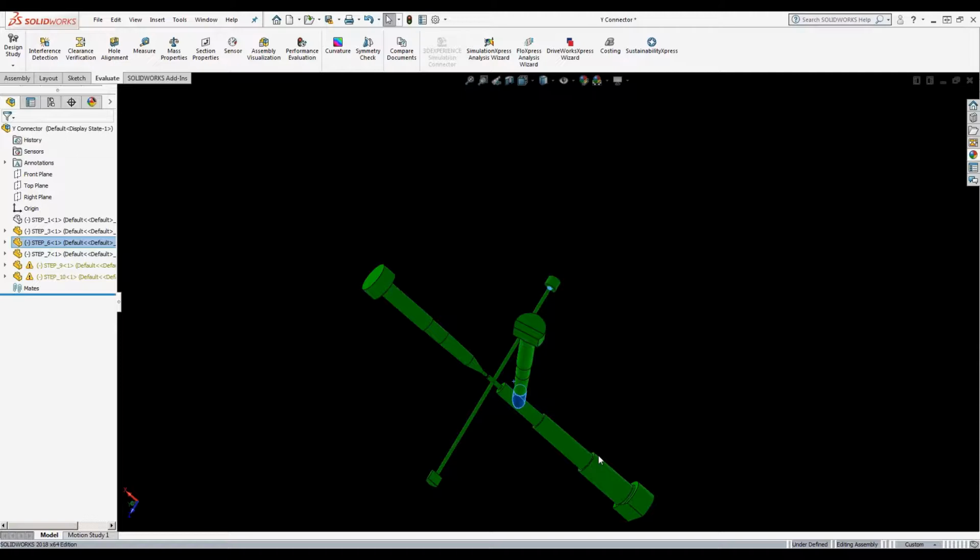Okay, and it looks like we had a question on the first part, maybe leaning towards the same question. On the first part, are the side pulls hydraulic or mechanical slides? If mechanical, how do you keep the small hole cores from being damaged from the mechanical slides as the tool locks? On that tool, we can pull it back up, but the part of the tool that created those small through holes was actually in the cavity of the part, I believe.